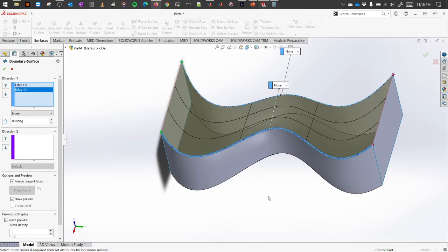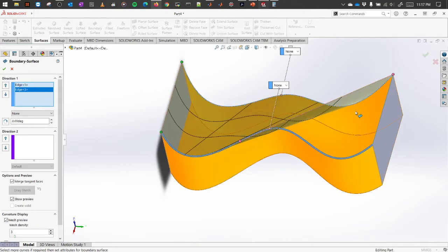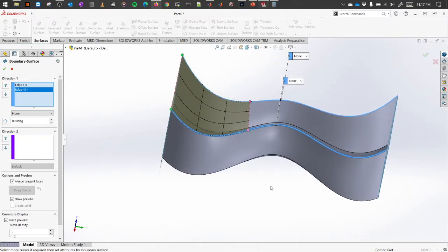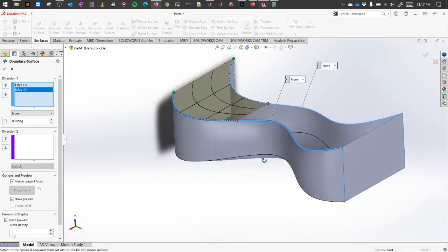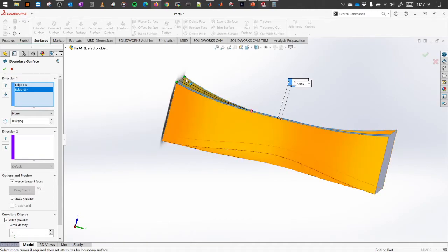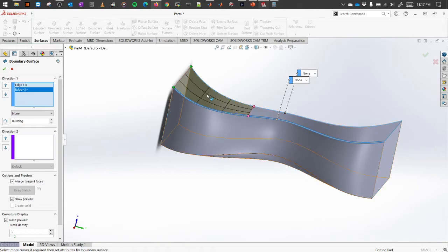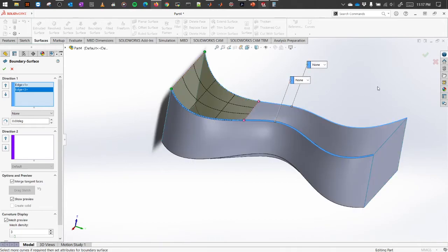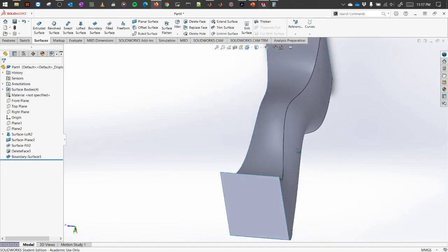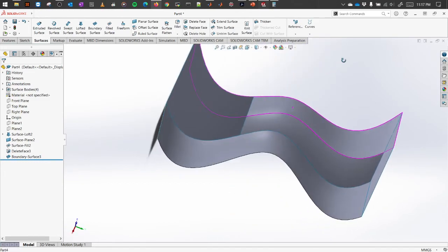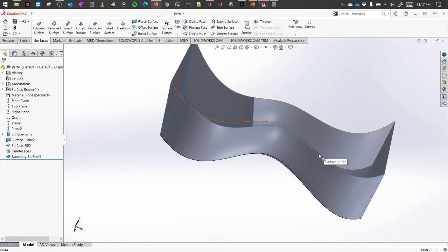We can also modify the surface expansion or select only a portion of it. So as you can see, these pink points here, you can just drag it to select only a portion of it. Let's say we want to only create surface till this point here. Okay, so everything will be as is closed, and as you can see, this is not on the same plane, so it doesn't matter, it will go along the edges, and once you're done, click OK. It has only created the surface for that upper portion. Other than that, it is still open and empty.